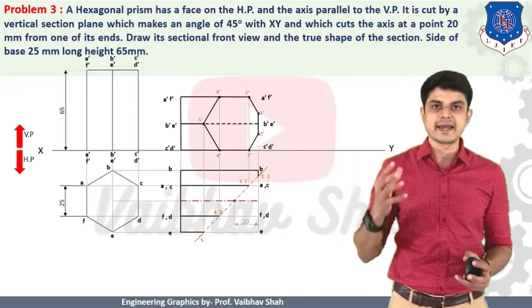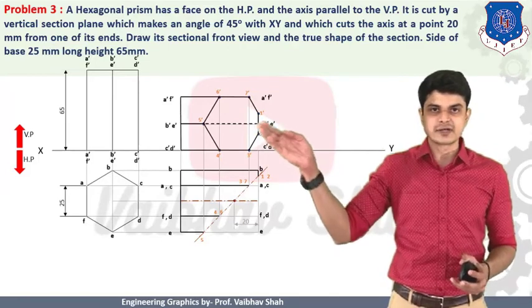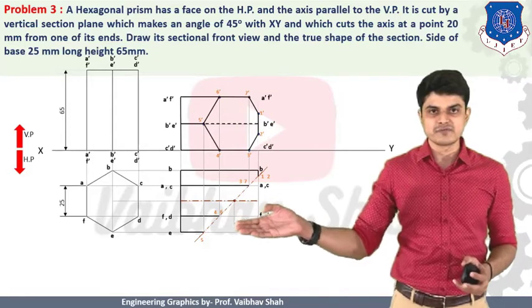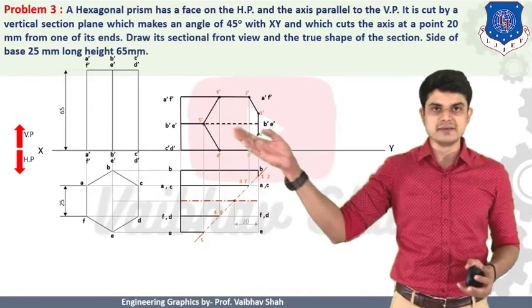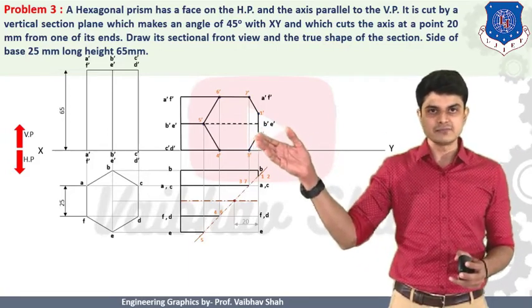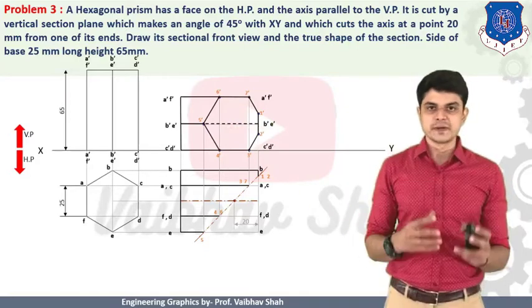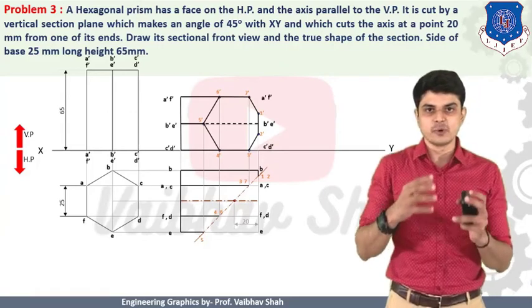A required hexagonal prism. Here I have drawn this line with a dotted line because when we try to take the front view from this direction, it is obvious that this BB line will not be seen. So we should put that BB line as your hidden line. So I have put this dotted line. But here, as you can see, there is a solid line on the left hand side because it is superimposing the line of E. So here BB and E line coinciding each other.